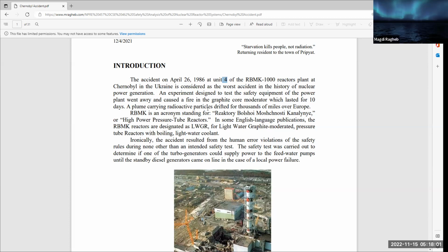So let me explain it in more detail. Suppose I have a perturbation where the temperature in the reactor increases. If the temperature in a light water reactor, the pressurized water reactor or the boiling water reactor, increases, you'll find that the voids in the coolant increase. So the void increases, the number of molecules per unit volume, or the density of the coolant, decreases. As the density decreases, the moderation of the neutrons decreases, and less power is produced. So you find that the temperature that was increasing as a perturbation goes down. The system becomes self-regulating. We call this negative feedback.